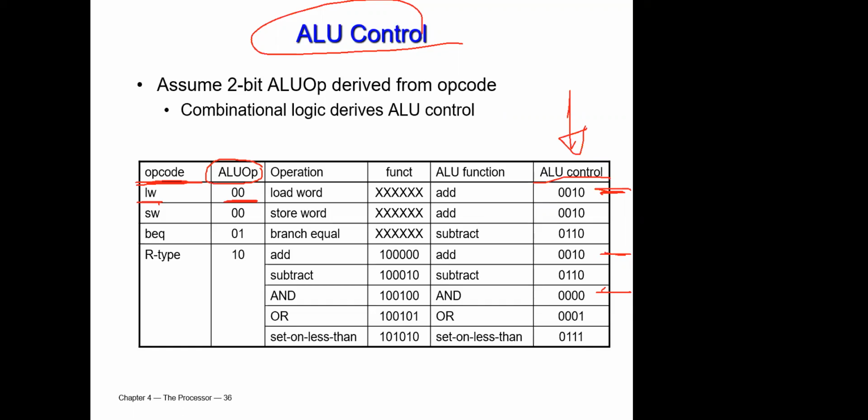Okay? And then I will do an addition, because with the addition, I can add plus or I can add minus. So I can make it easier: as soon as I see a load word or a store word, I will have exactly the same ALU operation, and it will ask my ALU control to have an output of addition.